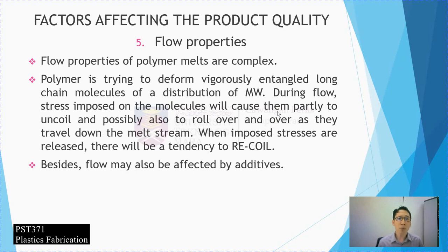Besides, flow may also be affected by additives. Some of the additives will increase the flow properties, that is, the viscosity of the material. So some of the additives may make it unable for this material to be processed using certain equipment. For example, extrusion blown film requires a very low viscosity, and at the same time requires more stability during the blown process, or else it will start to collapse.